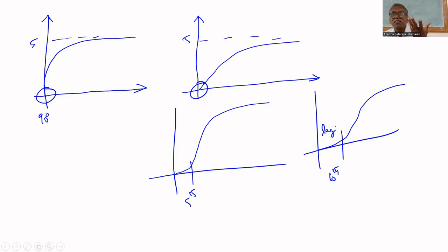If it is an algebraic model, zero order means as soon as the signal is changed, all cars will move together. That can be done only in mathematics. In practice, it is not possible. So you have to wait. If it is the 10th car, you have to wait more. For the first 10 seconds, there won't be any movement for the 10th car. So if we cascade many first order systems, there will be a delay in the output.